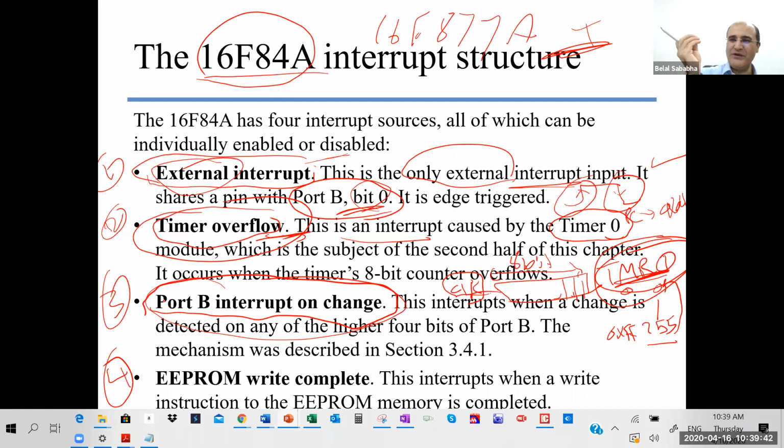One captures the port B pin value, but after you read port B, this is latched, and another one starts capturing the value afterwards. If these become different at any point in time, the XOR will output a 1, since any two differing inputs to an XOR cause a 1. We get the 1, and this will trigger an interrupt. Go back to chapter 3 to check it.